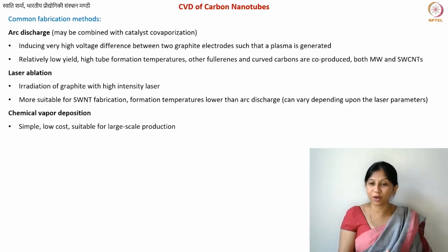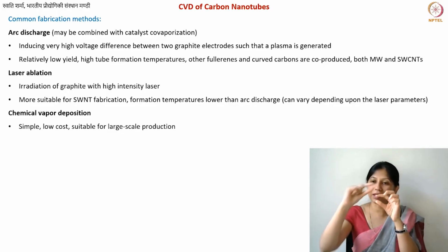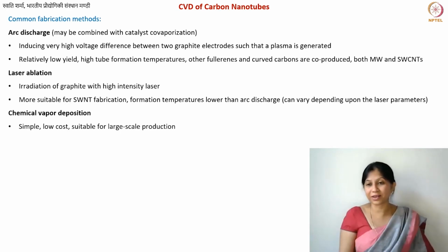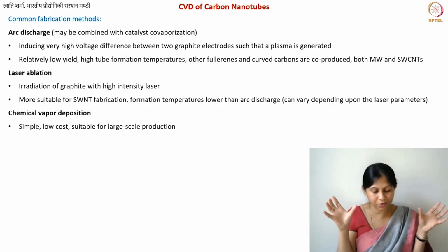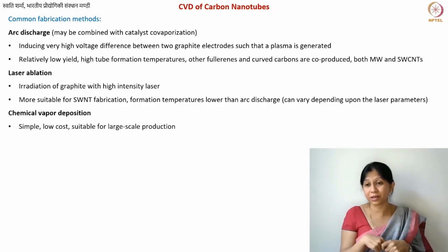In fact, in the case of pyrolytic graphite production, we are using graphite itself as substrate, you know that, okay? So the point is that if you have a catalyst particle, then you have one layer of carbon deposited on it. Then there will be a second layer deposited on top of that, and the third layer, and the fourth layer, and the fifth layer, and then what you get is a tube-like structure. That is what we call carbon nanotubes. So how are we controlling the diameter of our nanotubes here? By controlling the diameters of our catalyst nanoparticles.